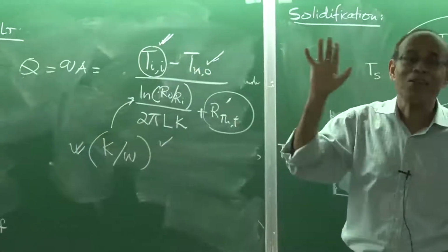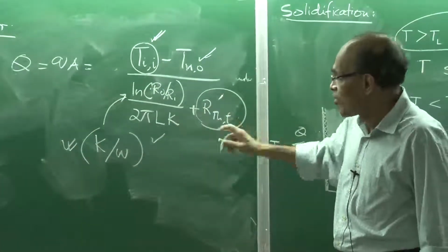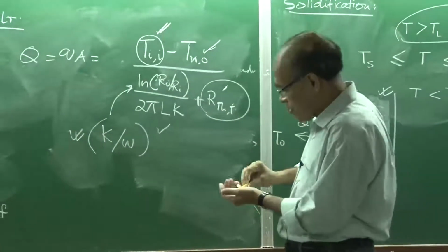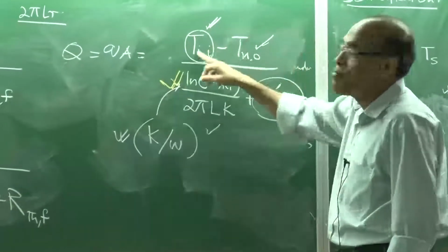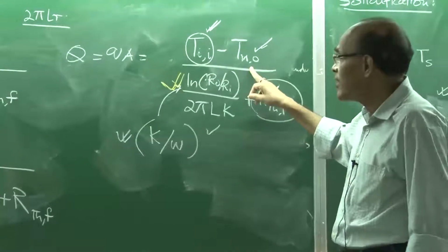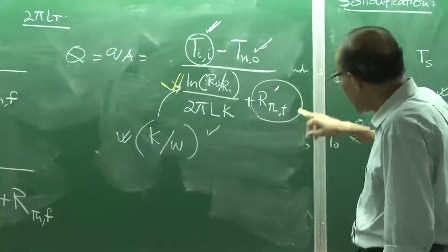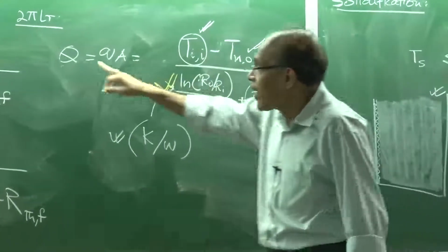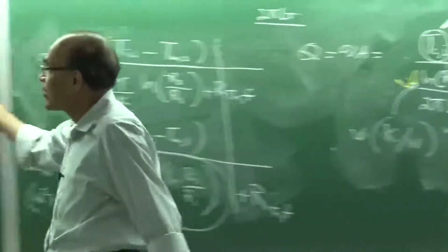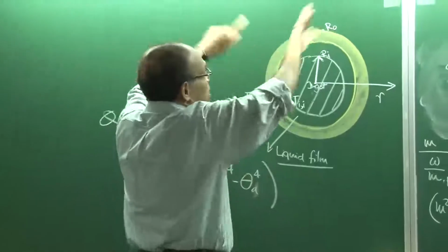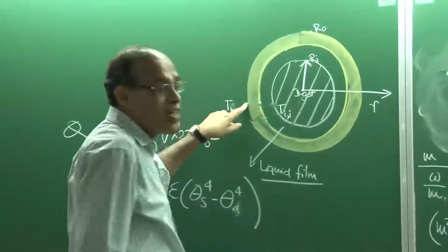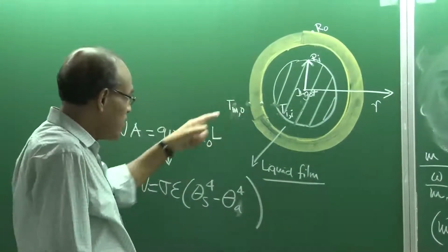That is the whole thing, because you have one equation. As I have indicated, this term is known to us, this is known to us, this can be measured in the industry, and this can therefore be found by equating the flux with the net radiation taking place from the ingot surface, the heat being lost, because the temperature here is going to be 700, 800 or 600 degrees centigrade.